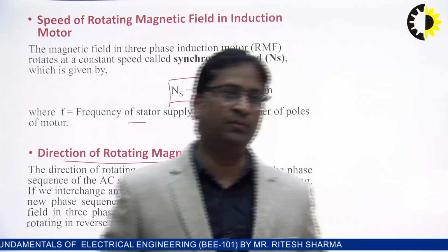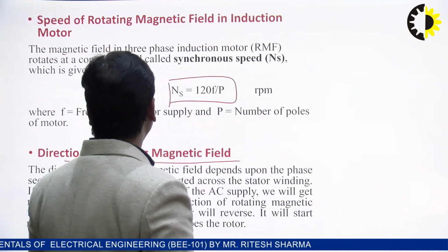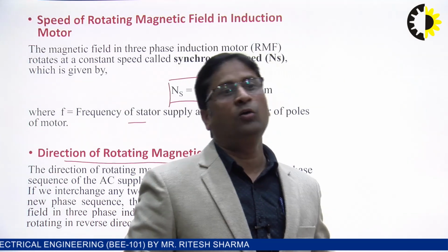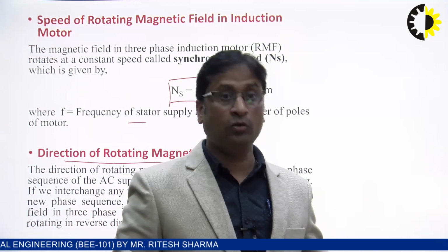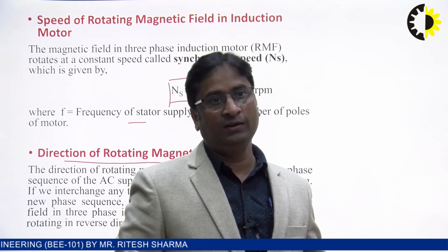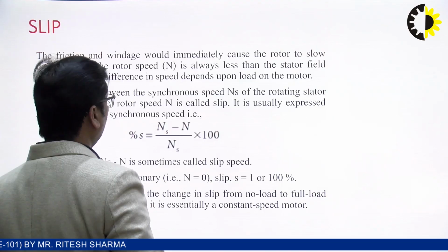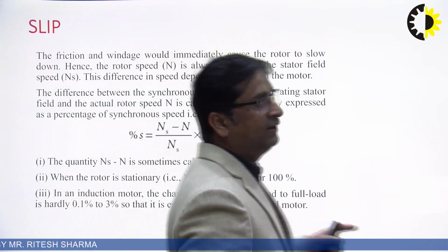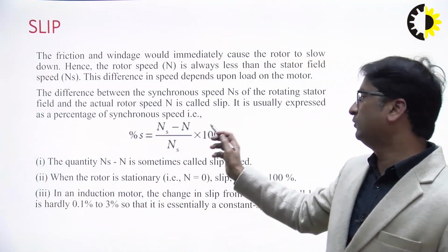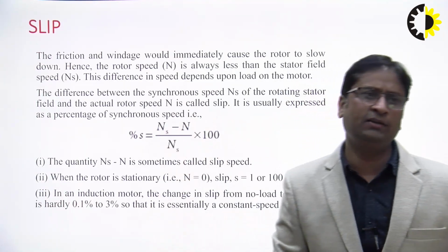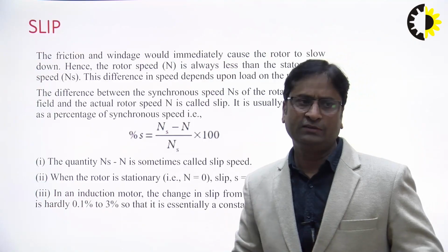So this is the basic concept for the three-phase induction motor. How this rotating magnetic field can be developed. And the slip, as I told you, is the ratio of the relative speed between the synchronous speed and the motor speed with respect to the synchronous speed.